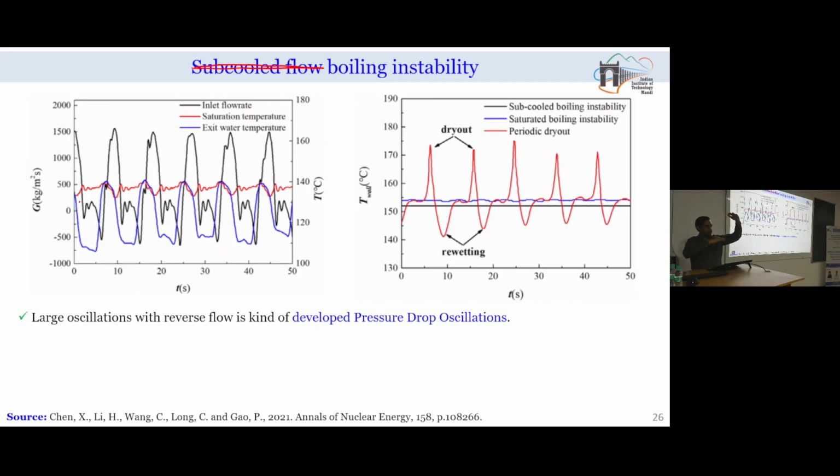Once it is closing the entire portion of the tube, the pressure on the vapor side or outlet side of the heater will become larger in comparison to the pressure at the inlet side, and in this scenario I will be finding some sort of reverse flow. So here you can see when a significant amount of vapor starts forming, then we get the reverse flow. Instead of moving water in the forward direction, water will also start coming in the backward direction. And what is the consequence? Whenever vapor is forming at the heater surface, you are supplying continuously electric heating or any other type of heating, but vapor is not able to take the heat.